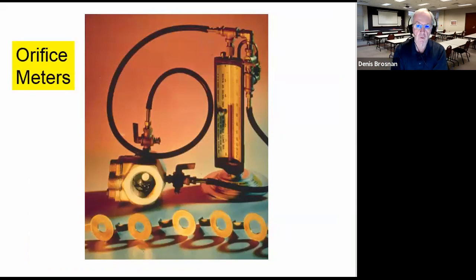Now for flow within the pipes in the system, gas or air, we use an orifice meter. An orifice meter has an entrance in and an exit in. You measure the pressure on the entrance in and the pressure on the exit in. And these pressure impulses are hooked to a U-tube manometer, okay, that's filled with a fluid so that we can easily measure differential pressure.